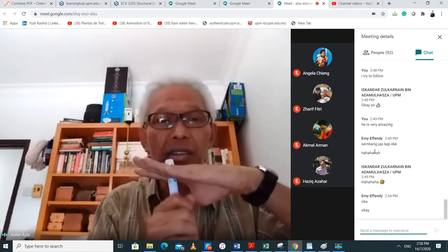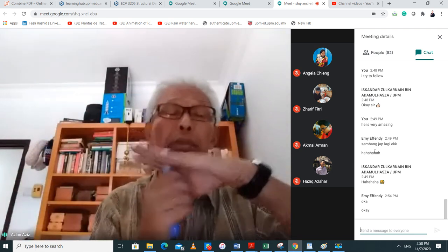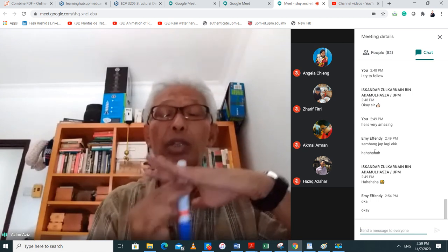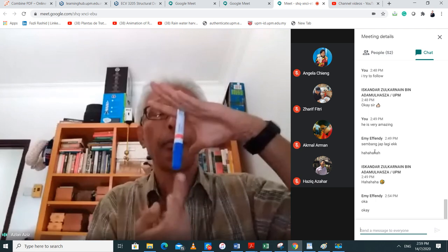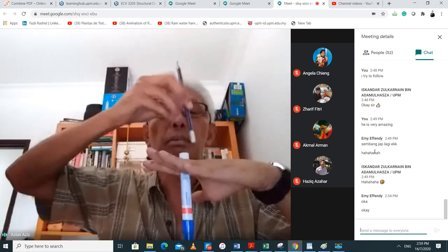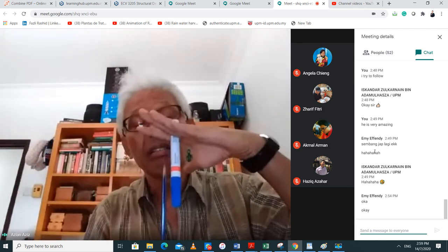Then there is a resistance from the friction because you're pushing it downward. So the soil around it reacts, opposite to the load. So it's upwards along the skin friction. Both are upwards. Load is going downwards from the column. In this direction, it is all positive.